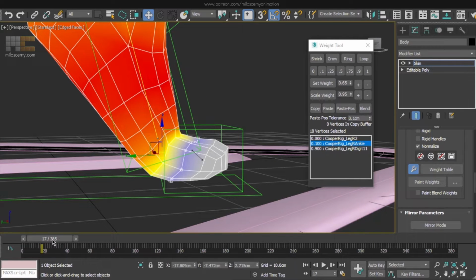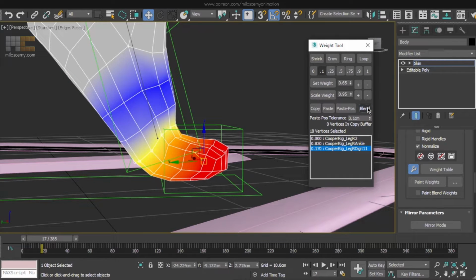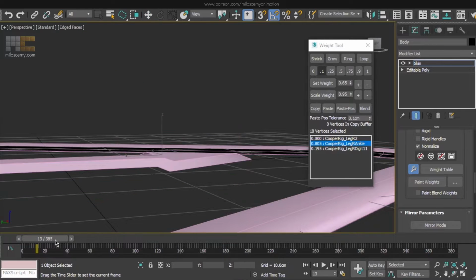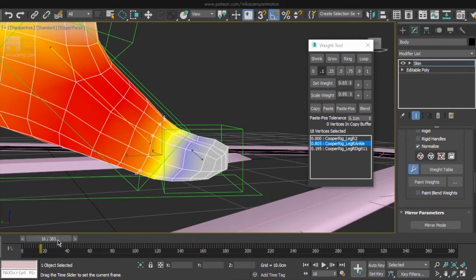So basically now I have explained to you all the tools there are to skinning, and the whole process is just using these few things to get the best result you can achieve. So for this loop, let's try blend. But that's too much, so remove the weight a bit. Or add it to the other bone. And this over and over. It needs a lot of practice of course, but we will get through the whole model here, so don't worry, you will learn a lot.